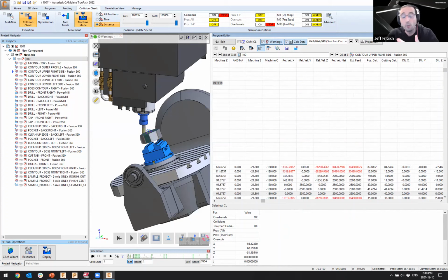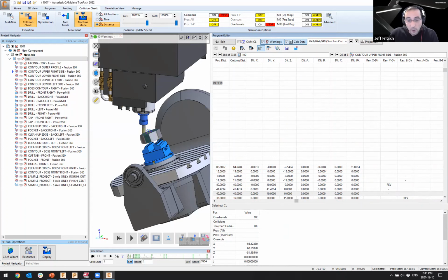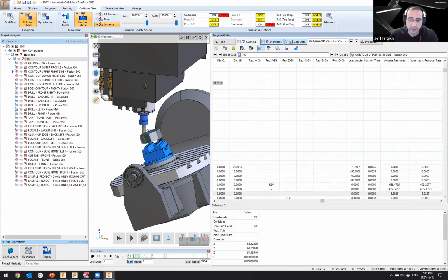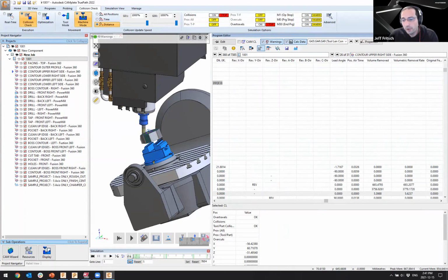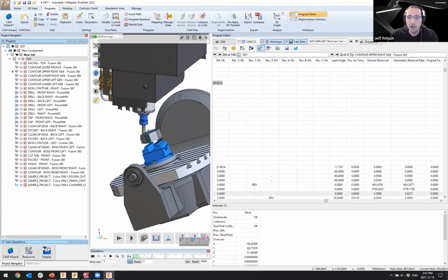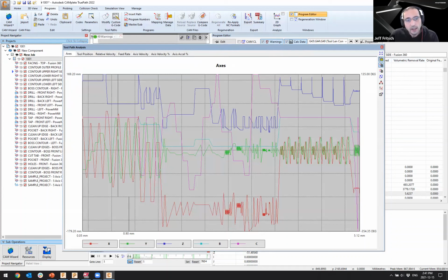Where's the machine at? Where is it going? How fast does it go there? What is the shortest way? Is that a feed rate that's actually within the range of how fast the machine can move? And what I'm more interested in here, and wanted to highlight, is the volume of material removed and the volumetric material removal rate. I know that's a mouthful, but what that means is now we can use all those data points to build that picture of the process and identify any possible issues